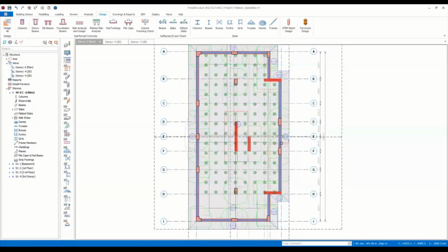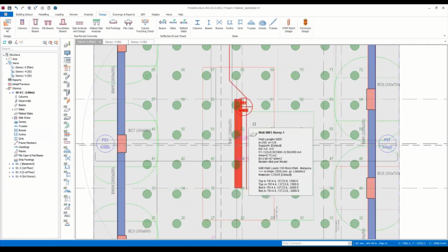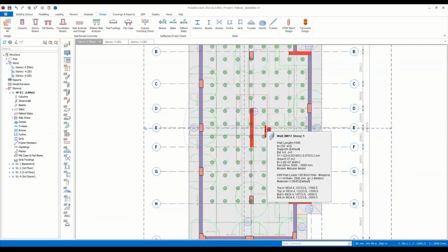And as you see, all of the punching parameters will be drawn on the plan view. Also, we have a failing member, which I'm not going to try to make okay. What you can do is increase the slab thickness, or you can make some geometrical changes in the section of this member. You can make it larger to dissipate the stresses better.